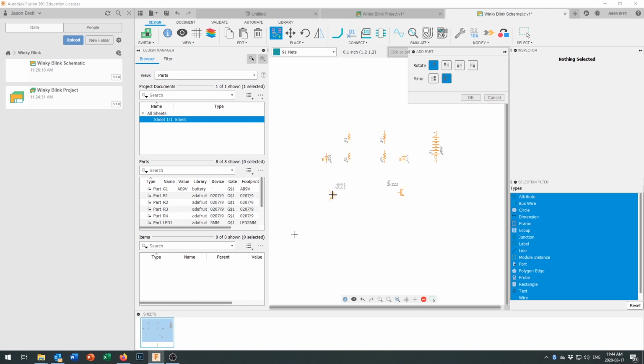Now, we don't want to do any mirroring when we're making our printed circuit board. When you mirror something in your printed circuit board, you're going to run into a problem because it flips it from one side of the circuit board to the other. You're messing with a physical part. In schematics, because we're just talking about the idea of the transistor and not worrying about its actual physical size or anything like that, we can mirror away on these parts to our heart's content.